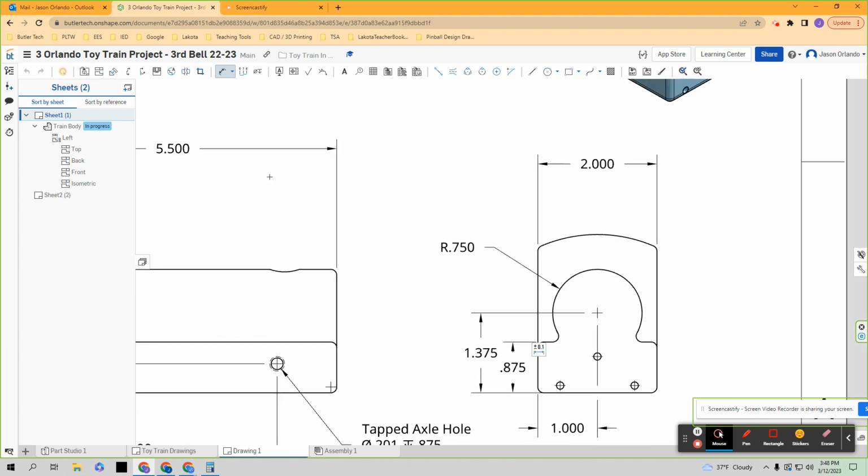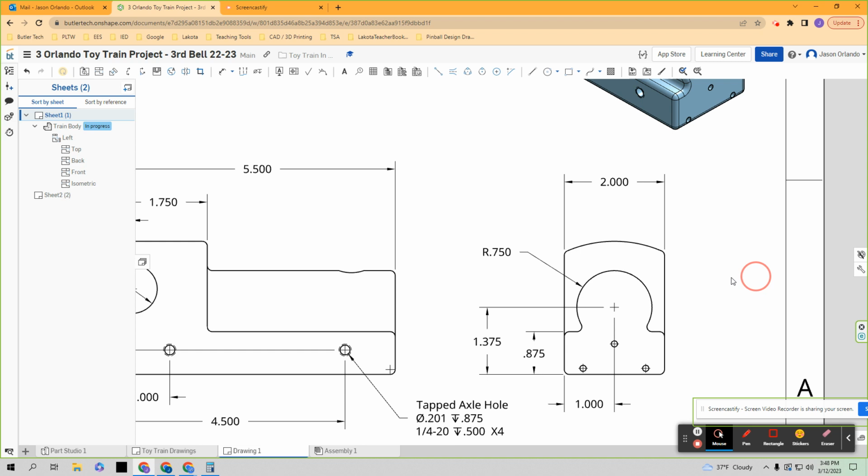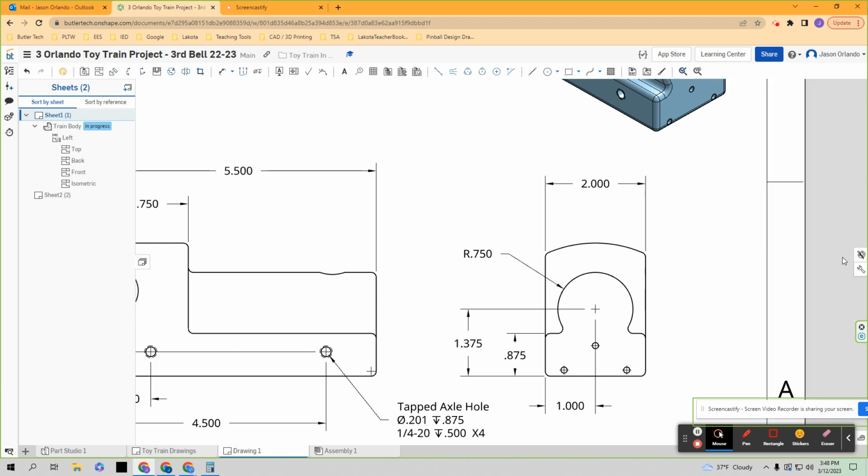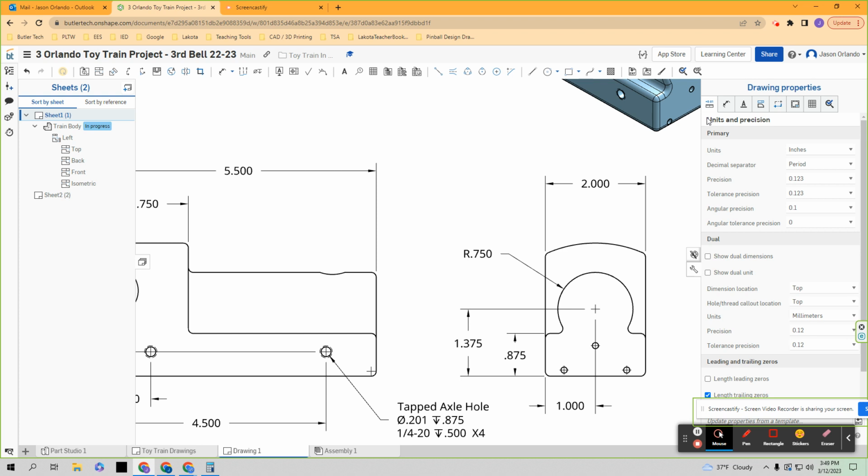Now, if your dimensions start getting really close and cramped, you should pull them out. Just space them a little bit, grab them and manipulate that. The other thing that I've done that I probably need to do again here is I can control the font size and the arrow tip size, and that sometimes gives me just a little more space. So I did choose to pull out this wrench. I should have done this at the beginning, but I didn't.